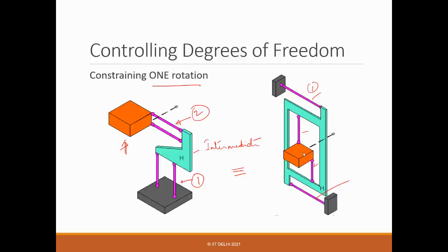In the perpendicular direction, so one is in this fashion, the other will be in this fashion. If you simply connect this and then connect this, what you get ultimately is the rotational constraint for this. You can see out of the plane it can easily move and rotate, so you will get all the other 5 degrees of freedom.